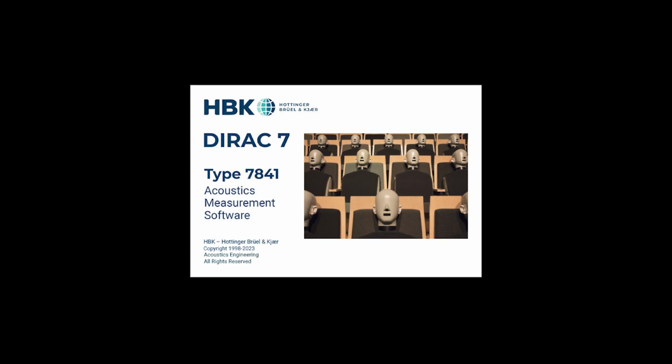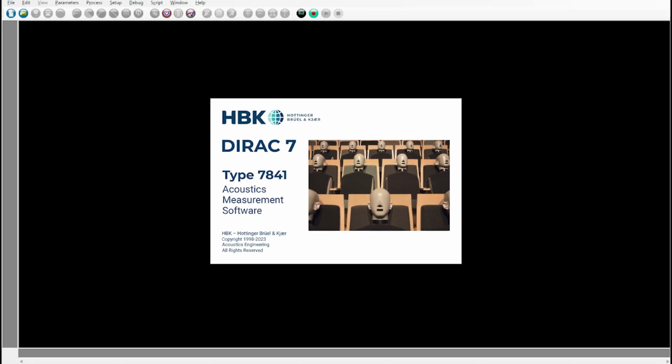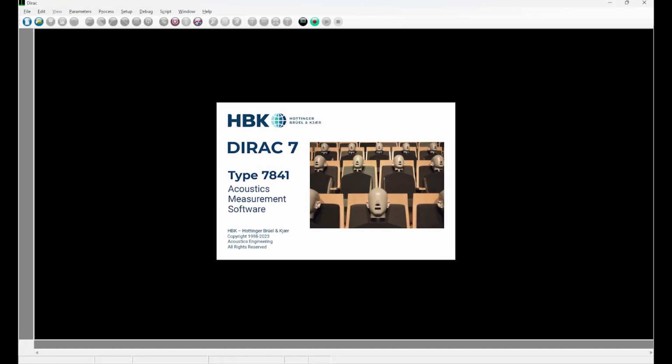This video will demonstrate how to measure and analyze the reverberation time of an office using Dirac. We want to know the reverberation time in each octave frequency band ranging from 63 Hz through 8 kHz.